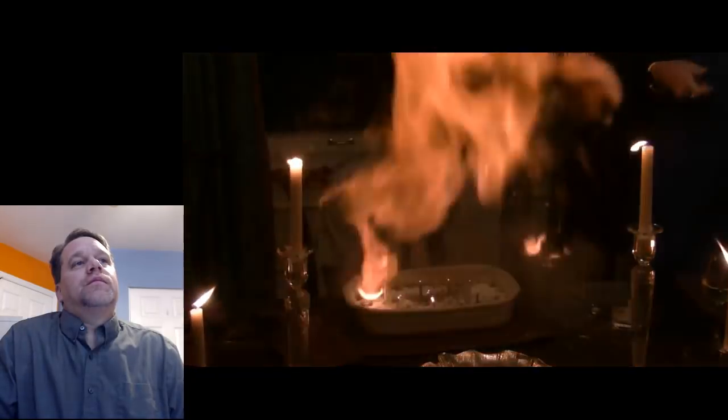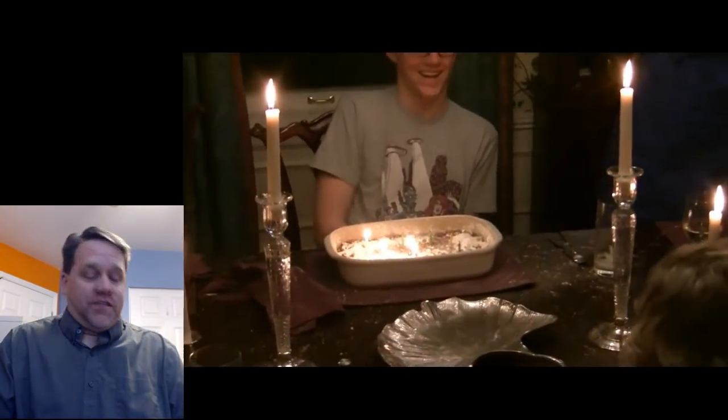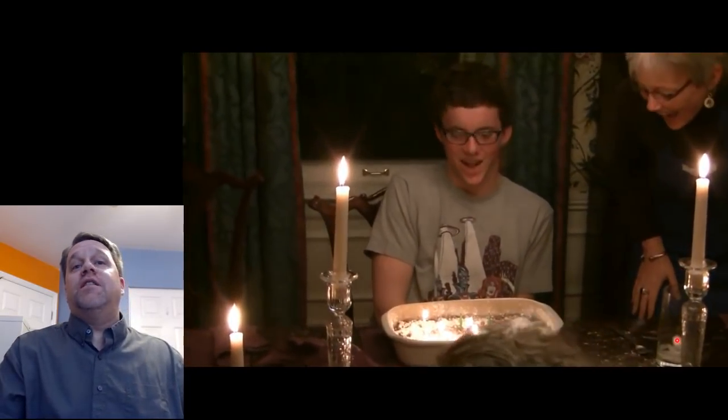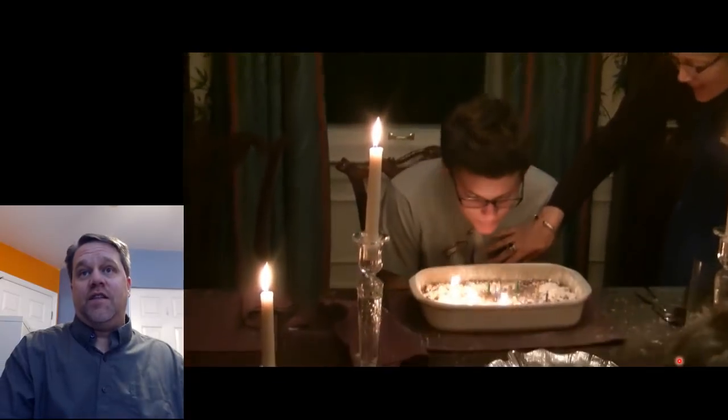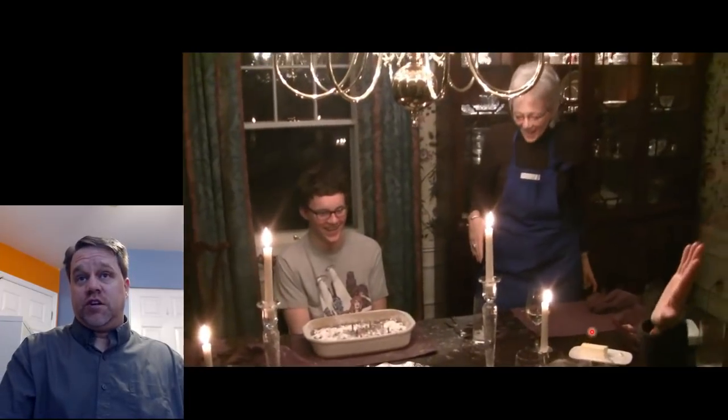I'm not saying don't try this at home, but I'm not saying do try it at home either. That's the difference between suspended combustible dust and accumulated combustible dust. When it's suspended in the air, it is particularly nasty, and that's why it's a Division 1 location. When it's just accumulated, that's a Class 2 Division 2 location.